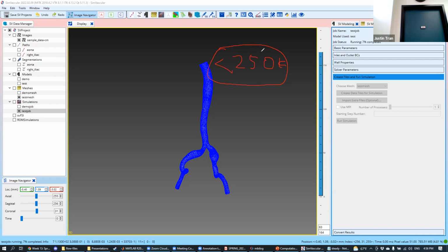So it's the other window that opens up, the one that's like the black box. Let's try this. Sometimes I've had success with unchecking this, so let's try unchecking it and running it again. Let's try a different algorithm. Let's try fast meshing.